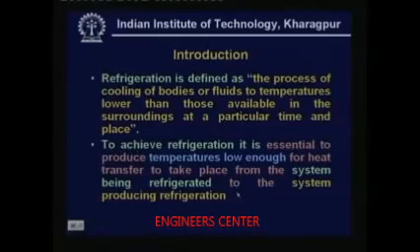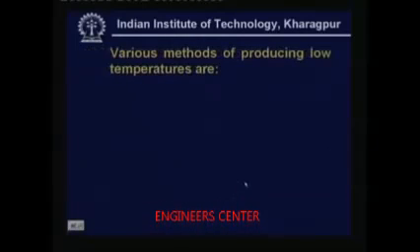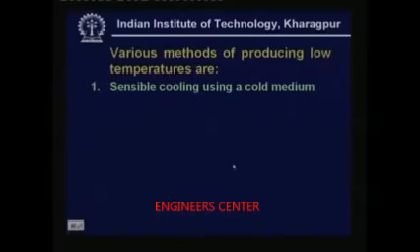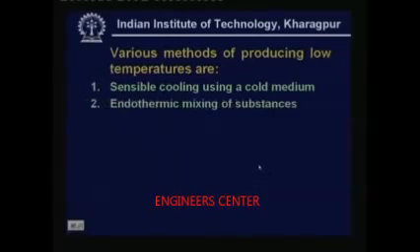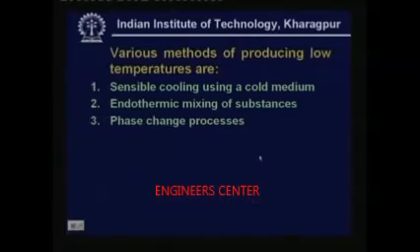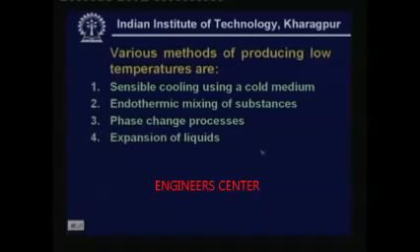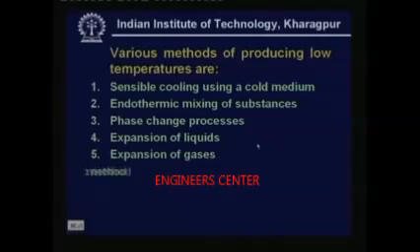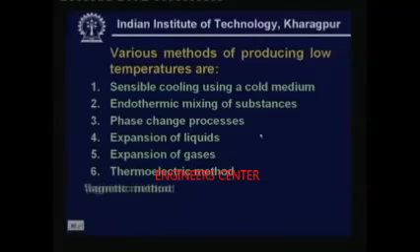So let us look at some of the methods of achieving low temperatures. The various methods of producing low temperatures are sensible cooling using a cold medium, endothermic mixing of substances, phase change processes, expansion of liquids, expansion of gases, thermoelectric method and magnetic method.